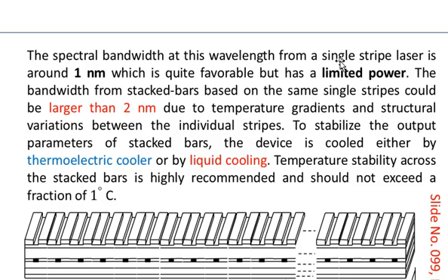You see that the bandwidth obtained from the single strip laser, which is of the order of 1 nanometer, matches very accurately with the absorption line of the Nd:YAG laser just mentioned. But a single strip will have limited power. The bandwidth from stacked bars based on the same single strips could be larger than 2 nanometer due to temperature gradients and structural variations between the individual strips.